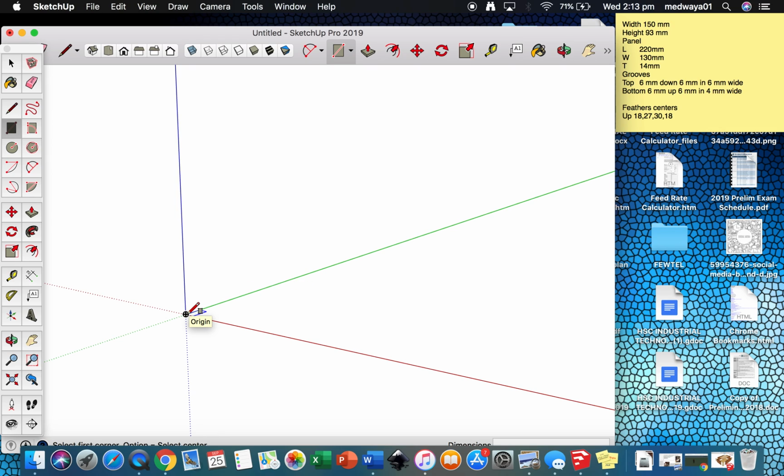Go to the origin, which is always the best place to start. Click once and just drag. Now when you click your finger down on the trackpad, lift it back up again, and then you place it again and just drag it in the direction you want to draw it. Already I've noticed I've got a problem. Down the bottom main corner I notice I've got feet and inches being displayed. I'm going to have to change that, but I can still type in a measurement.